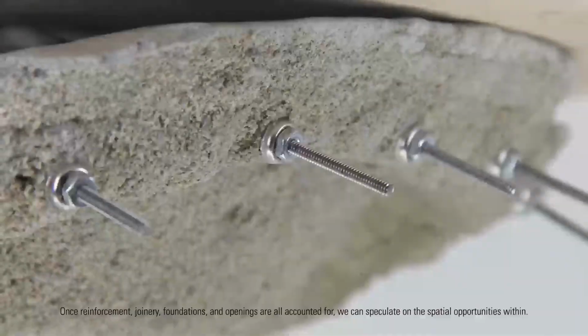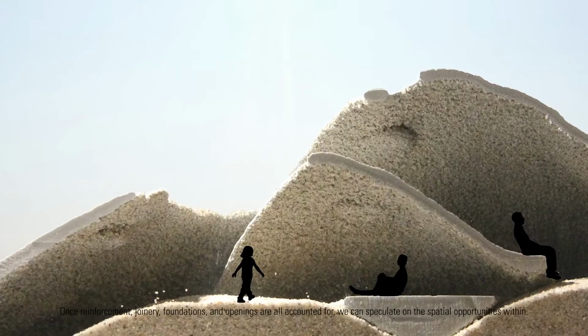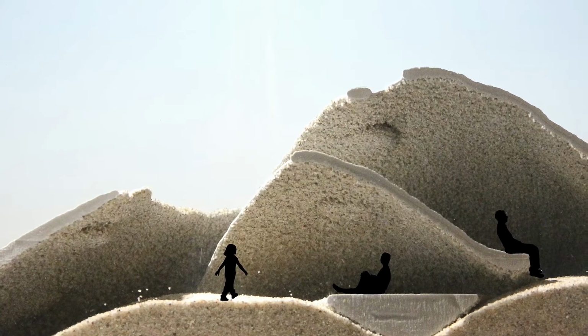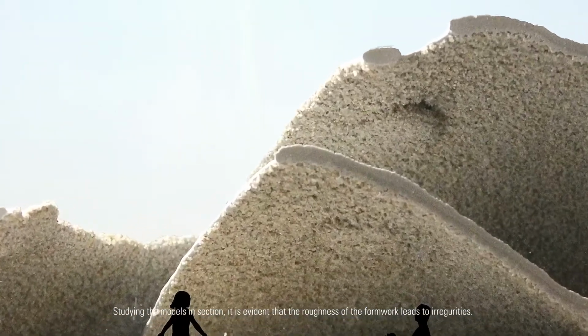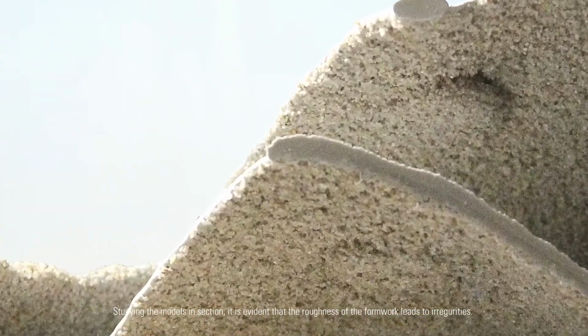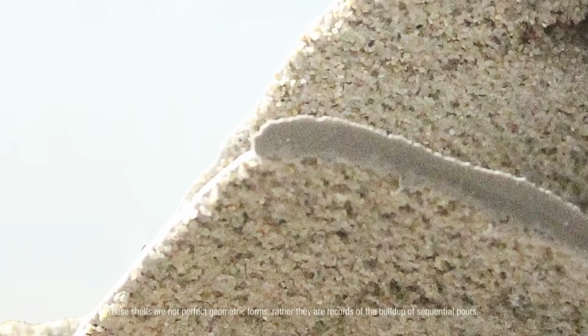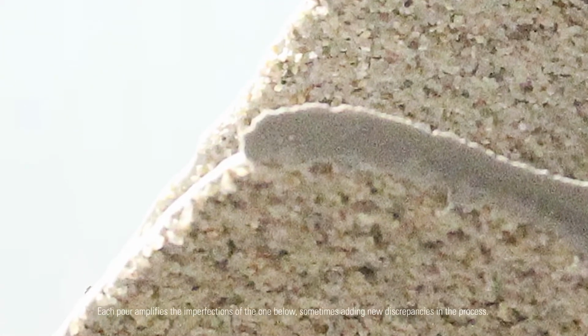Once reinforcement, joinery, foundations, and openings are all accounted for, we can speculate on the spatial opportunities within. Studying the models in section, it is evident that the roughness of the formwork leads to irregularities. These shells are not perfect geometric forms, rather they are records of the buildup of sequential pours. Each pour amplifies the imperfections of the one below, sometimes adding new discrepancies in the process.